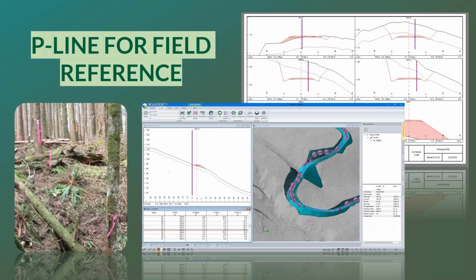So that stationing, our P-line stationing, is useful for when we go to build the road, rather than the builders having to have either GPS with them or some means of survey control. They can look at the tag, see that they're at station 650 or whatever it is, and then look at their design and relate that P-line station to where they're at in the design. So it's nice to know where you're at in terms of road length.